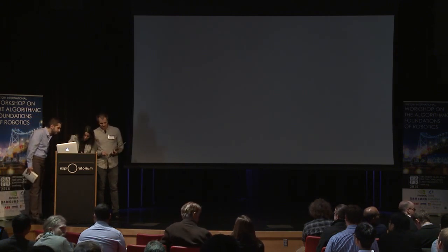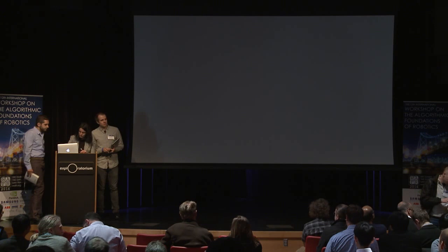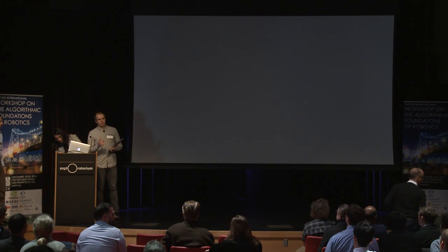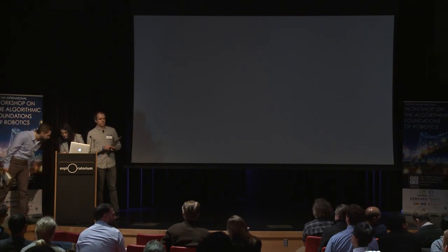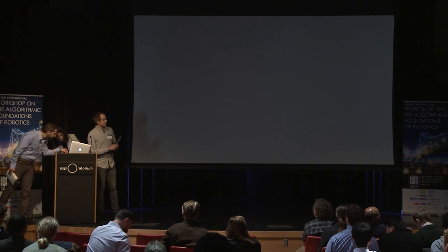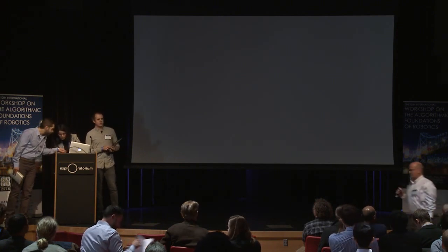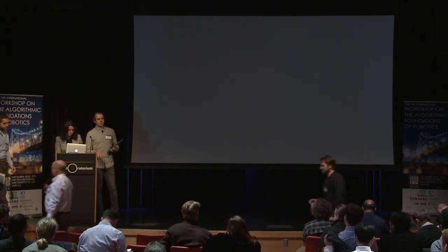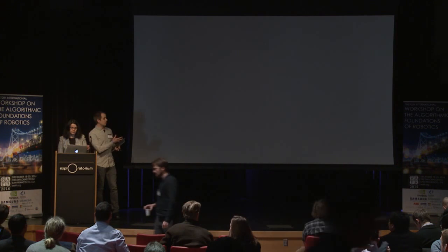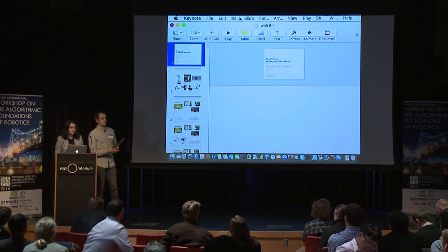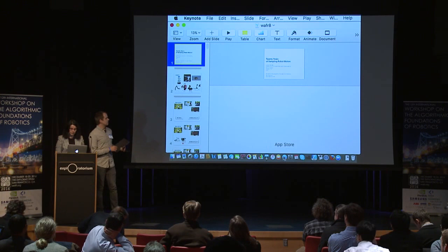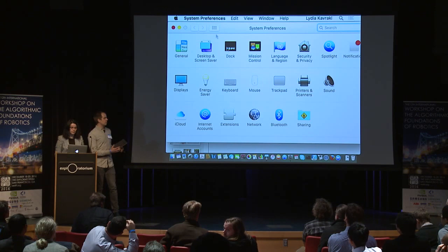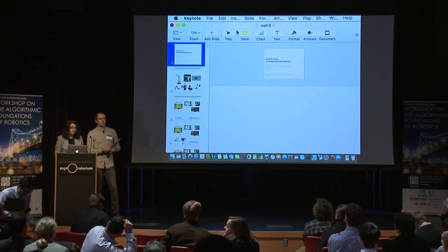Yeah, that's a hard question to answer. I would say we have just 15 electric motors in the robot, while humans have all these complex tendons and muscles and things like that. But one of the real challenges, especially with the walking that we're doing here, was that we have no load cells in our feet, so we have no contact sensing with the environment. We're also doing all of this walking with no torque sensors in any of the joints. So we have essentially only kinematic information that we're operating on to get this walking. And humans have a lot of feedback with their environment, which I'd say they use a lot in their locomotion.